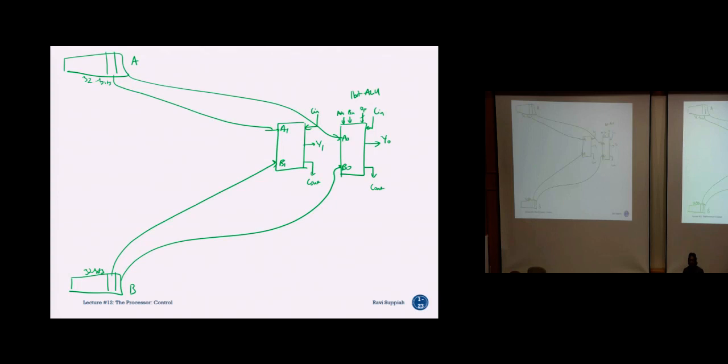So what do you see? When I supply 2 32-bit numbers, each bit goes to each of these 1-bit ALUs, all the way up to my last one, which is A31 and B31. So it propagates through all the 1-bit ALUs. And for each of these 1-bit ALUs, you provide your 4-bit control signals here.